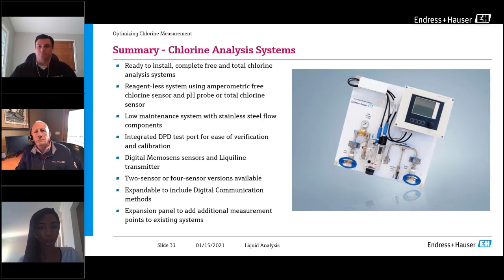Okay, thank you. The next question: is there a sensor to measure chloride content of the stream? Chloride content. In reality, I'm not sure I understand the question, but let me try and answer it anyway. In essence, a free chlorine sensor is actually not measuring chlorine or chloride. What it's actually measuring is hypochlorous acid, which is what you form when you add chlorine to water. And it's the hypochlorous acid that's a disinfector.